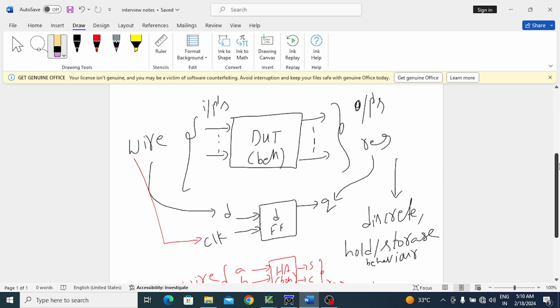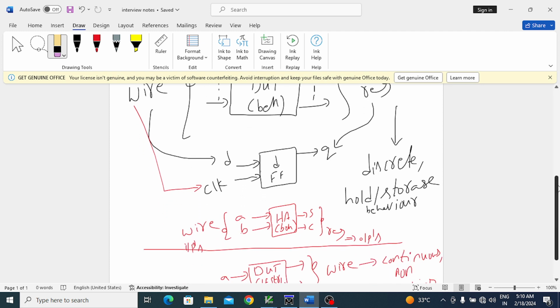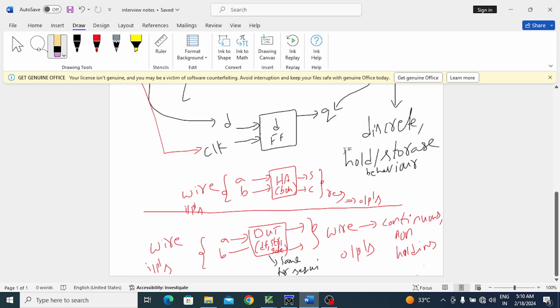We generally write not only sequential circuits in behavioral, we write combinational circuits also. You may think for sequential circuits storage is needed, that's why I write reg at the output, and for combinational circuits storage is not necessary. But even for combinational circuits we have to write reg for the outputs, if that output variable is on the left hand side of a statement in the procedural block.